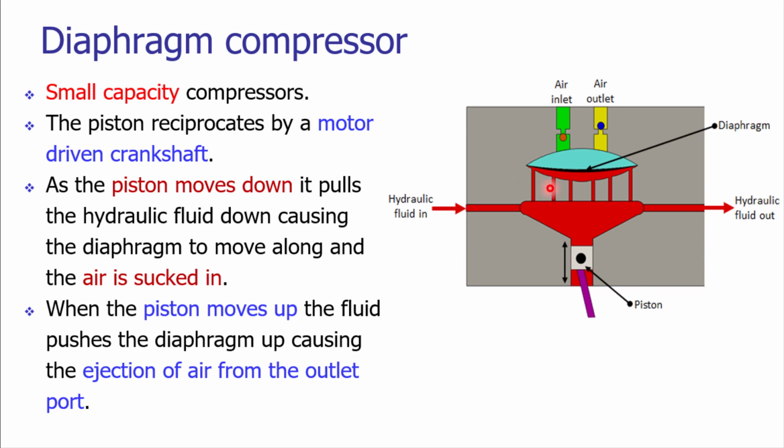So there are number of passages to the hydraulic fluid and there is a chamber. So through this number of passages or the channel, the pressurized hydraulic fluid will come to this particular chamber, and that chamber is having a diaphragm. So it is a metal diaphragm, it's a metal plate, thin plate, that is called as the diaphragm. And when the hydraulic fluid is pushed against this diaphragm, the diaphragm will be displaced in forward direction.